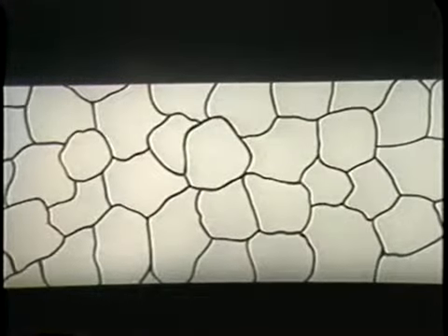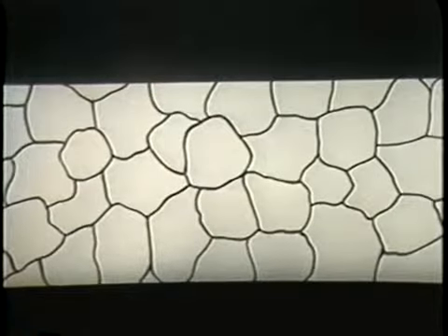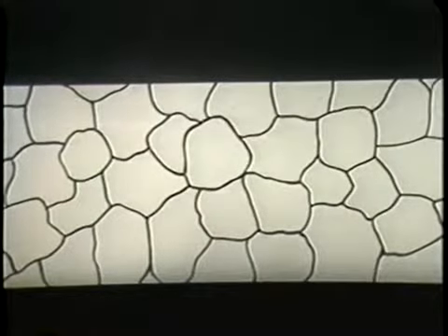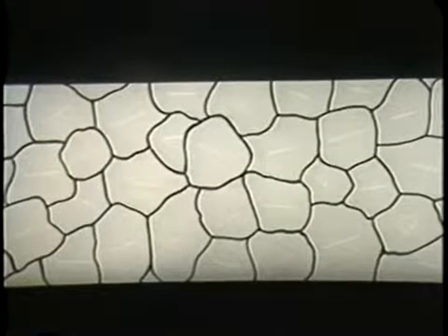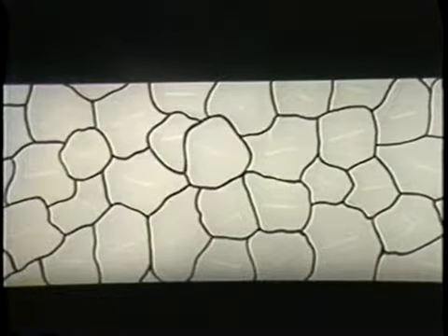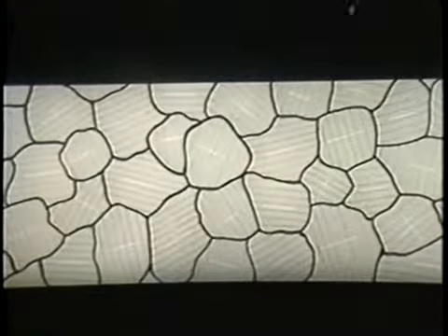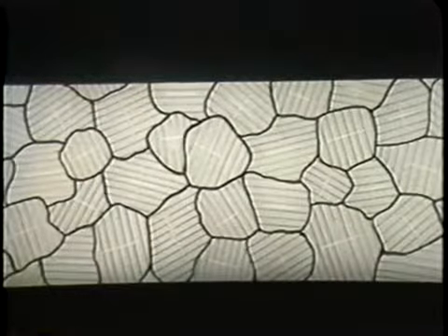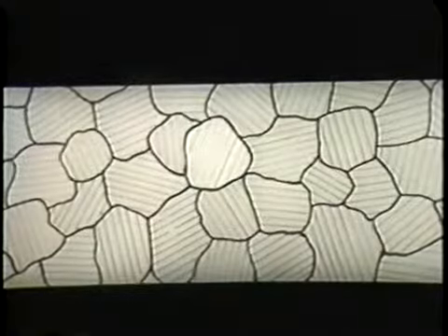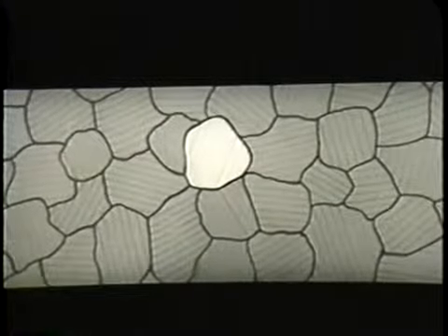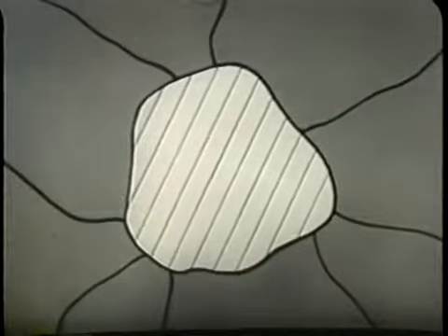Essentially the same action is involved in the plastic deformation of the polycrystalline grains composing an alloy specimen. Before deformation, these grains are randomly oriented, and the slip planes for each grain are lined up in different directions. When a load is applied to the metal, the stresses are transmitted from grain to grain. Some begin to deform by slippage before others. Within each grain, the crystal blocks rotate to produce elongation.